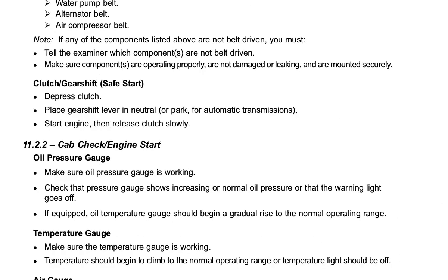Clutch gear shift, safe start. Depress clutch. Place gear shift lever in neutral or park for automatic transmissions. Start engine, then release clutch slowly.